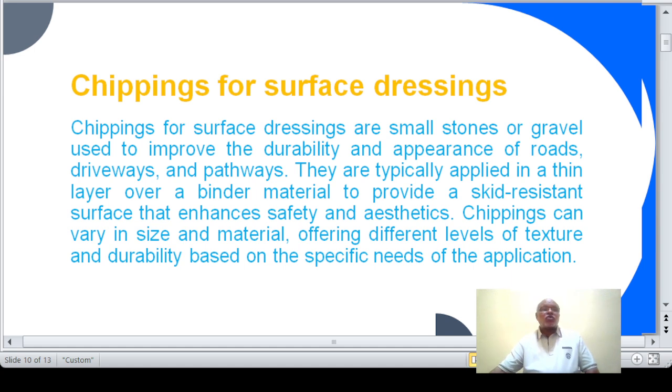The polished stone value required in a particular situation is related to the nature of the road site and the speed and intensity of the traffic. The resistance to skid is also dependent upon the micro texture of the surface, which in turn is affected by the durability of the exposed aggregate. This property is measured by the aggregate abrasion value.